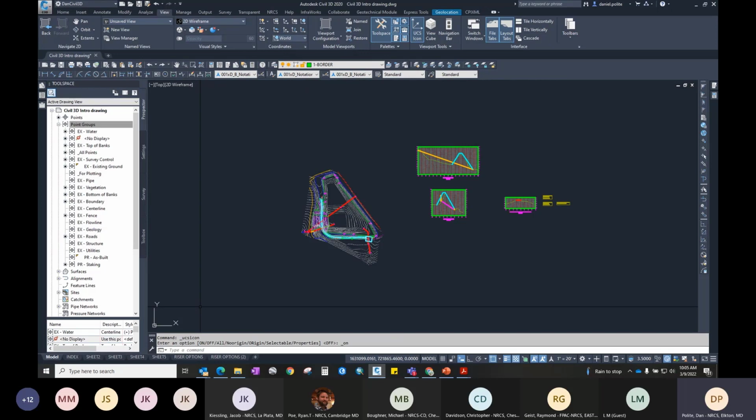Now, if you were to do a drawing that is not geo-referenced, even though your XY is shown this way, showing your north up, technically you might not have your north showing up here, so you might have to change that. If you don't have GPS, you will have to change that to make north go up, or you just adjust your north arrow to show where north is. But on most drawings, you try to have the north facing up as much as possible.